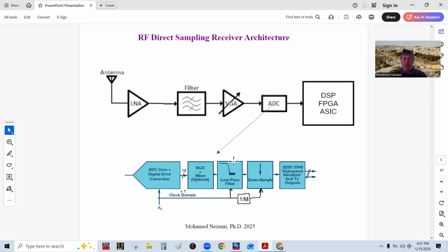The A to D that we have been talking about, if you refer back to the last session and the ones before, is an A to D that encompasses several DSP functions. Basically, once we digitize a signal in here, usually its center band or its carrier frequency is much larger than FS, or it could be smaller than one half of FS, meaning the incoming signal is in the first Nyquist zone or other Nyquist zones.